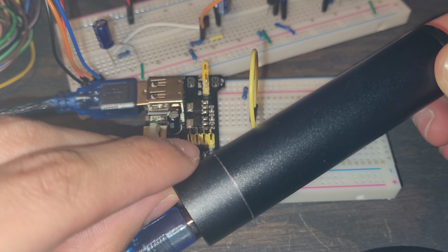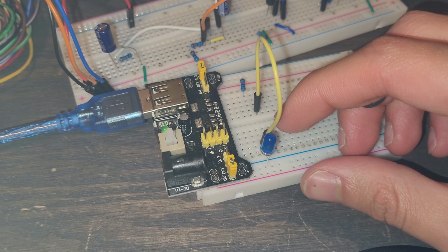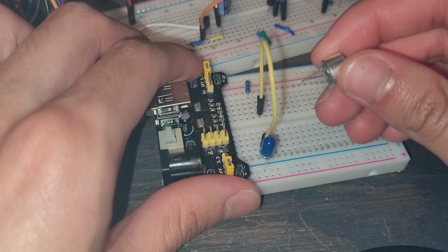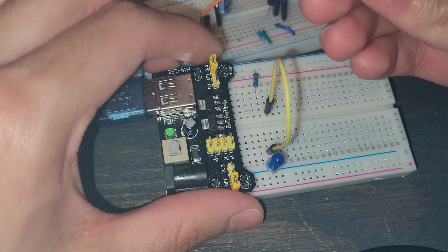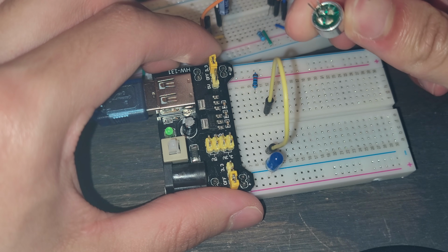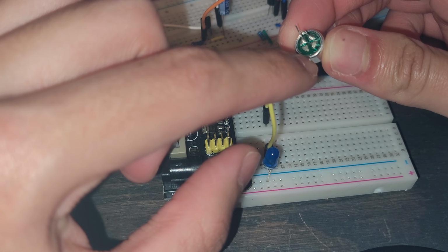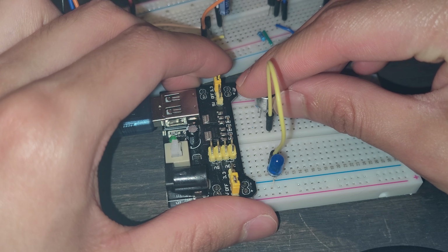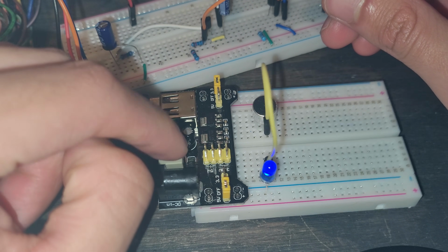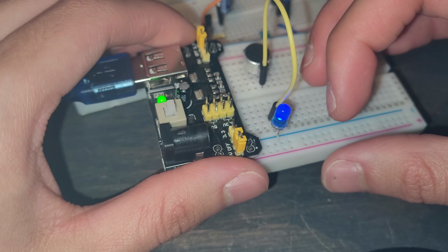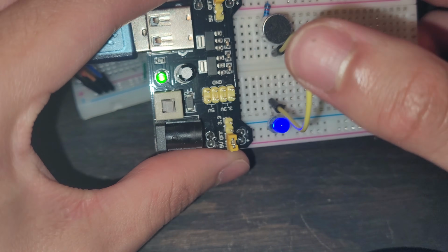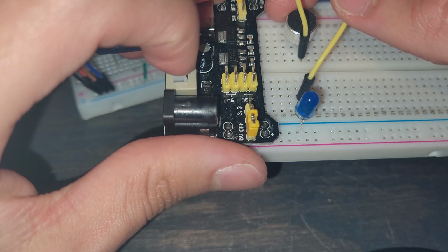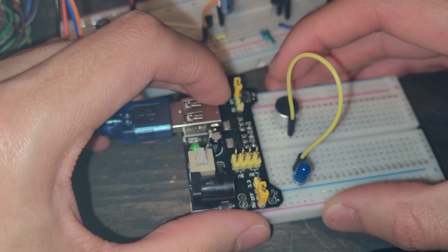So we have a battery here, and it's hooked up to this power supply. I'm going to just turn it on. You can see nothing lights. To complete this circuit, because currently it is an open circuit, we're just going to short it with this. We have our positive side here and our negative side there. And so we're going to just put this in and connect the two columns together and turn this on. We can see the LED turns on and lights up blue. It's very faint, but it does light up blue. If I turn it off, we can see that it turns off as well. So that's one way to test it.